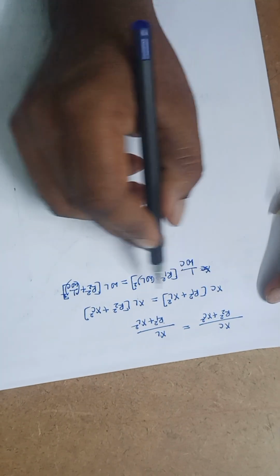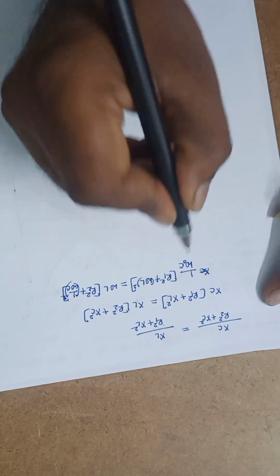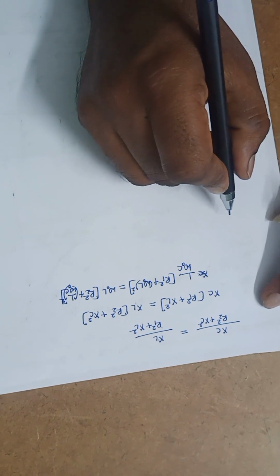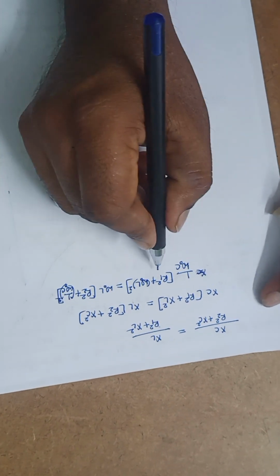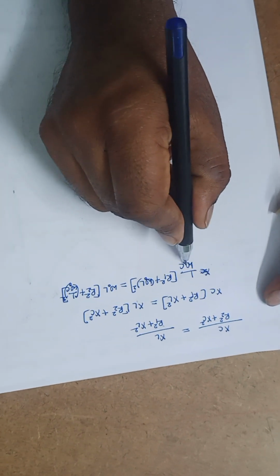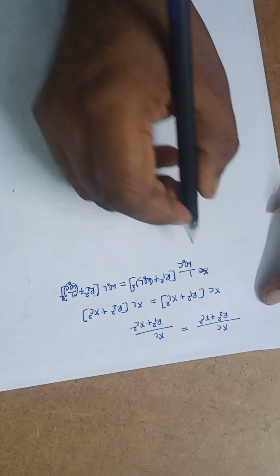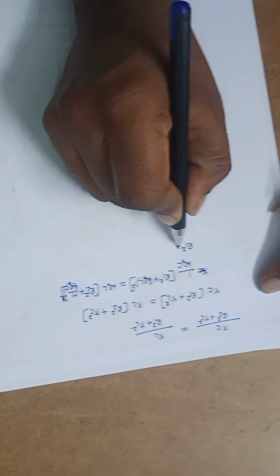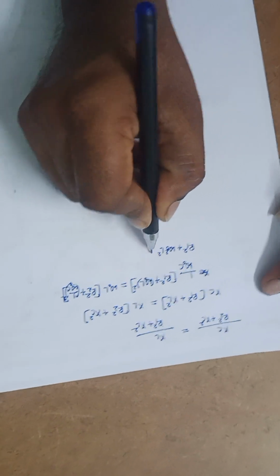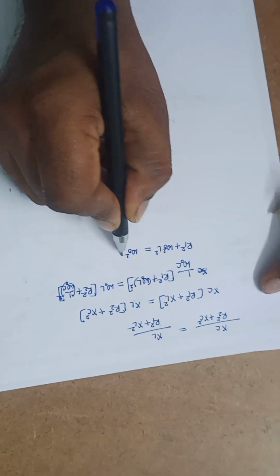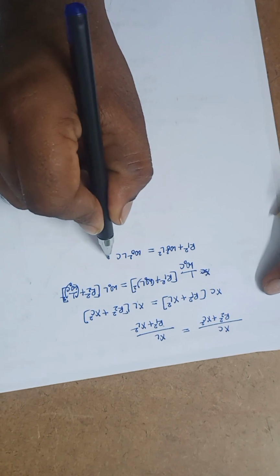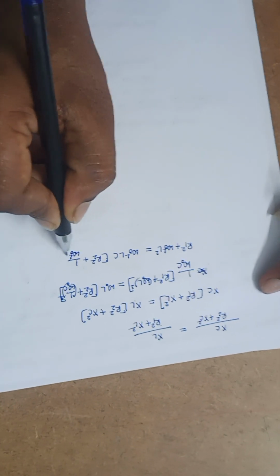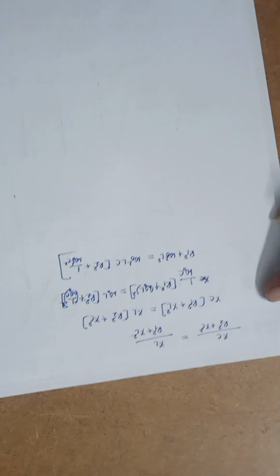Since it is under resonance condition, it will be omega naught. To differentiate the actual frequency from the resonance frequency, I am representing the resonance frequency with omega naught. Now just cross multiply it. R1 square plus omega naught square L square is equal to omega naught square L into C into R2 square plus 1 by omega naught square C square.